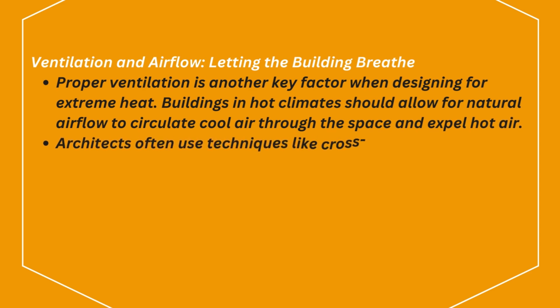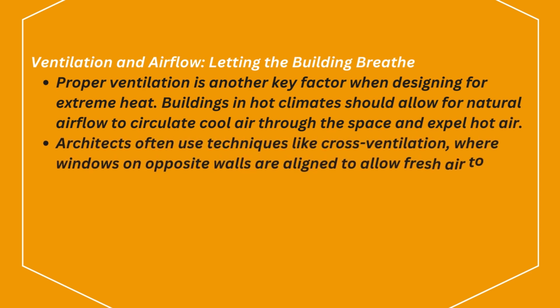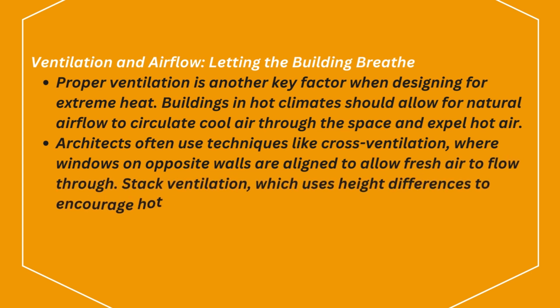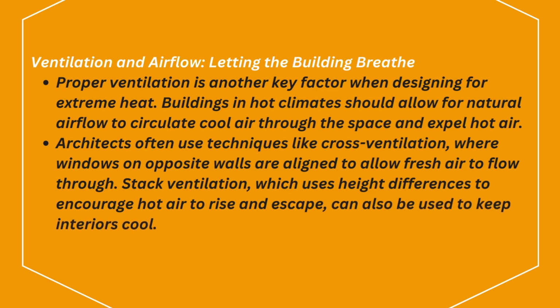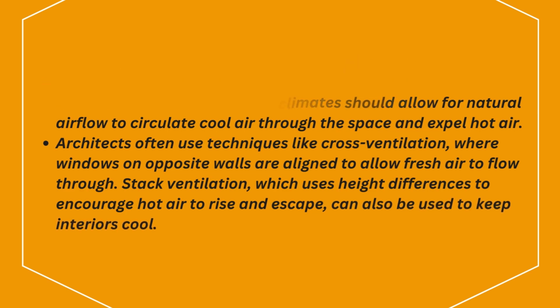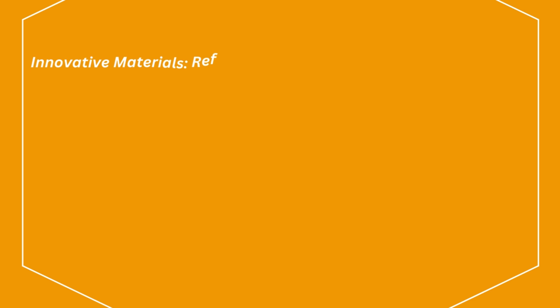Architects often use techniques like cross-ventilation, where windows on opposite walls are aligned to allow fresh air to flow through. Stack ventilation, which uses height differences to encourage hot air to rise and escape, can also be used to keep interiors cool. Innovative materials, reflective and heat-resistant.